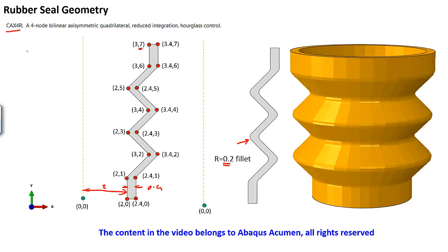One thing I forgot to put here is the units. It's Newton, millimeter, second and ton. So mass is in ton, time is in second, force in Newton, length in millimeter. So whatever unit you get, stress unit will be MPa.